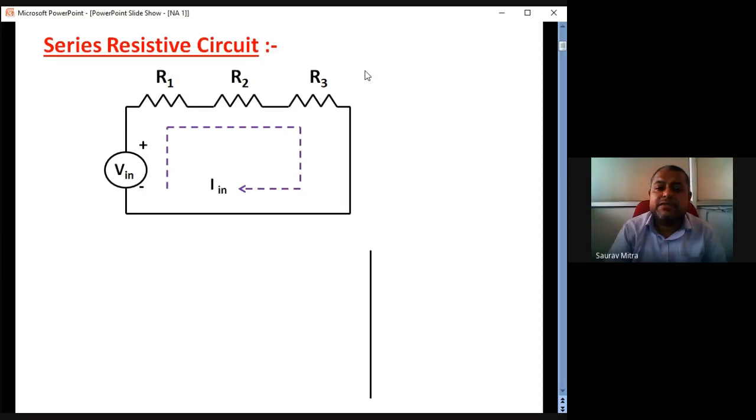Now resistor values, you cannot choose anything. Somebody just said 129.3 ohm. That is not possible. Okay, so there are some standard values of resistance which exist in the market. If I ask you if there is a 40 ohm resistor, the answer is no. If there is a 47 ohm resistance, the answer is yes. If there is a 470 ohm resistor, the answer is yes. If there is a 430 ohm resistance, the answer is no. So there are certain standard values of resistances.